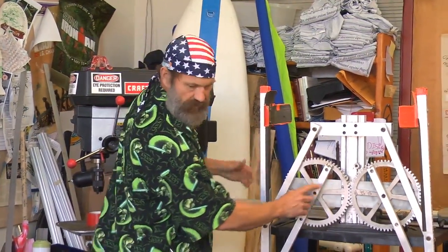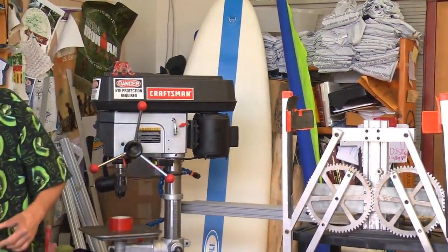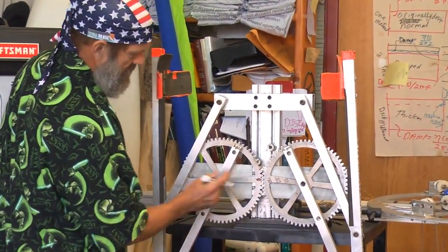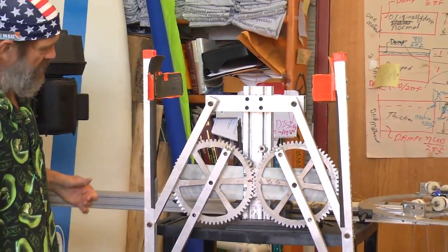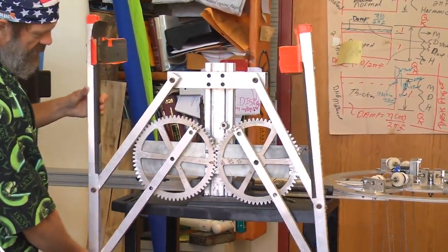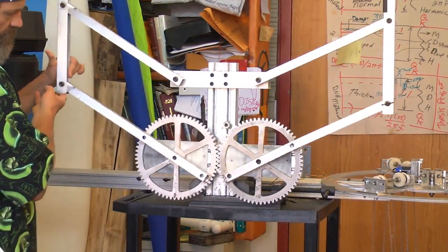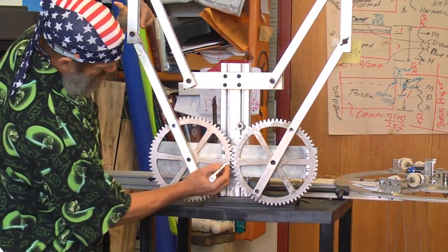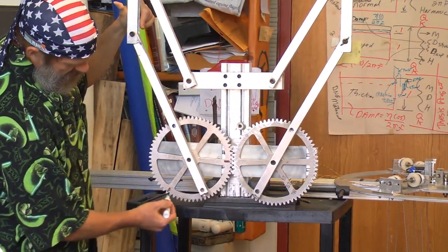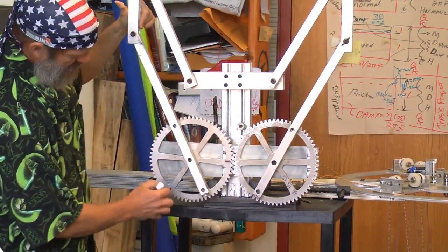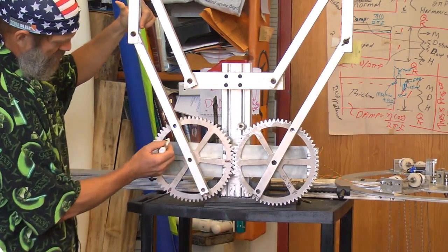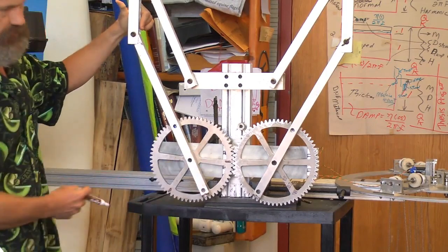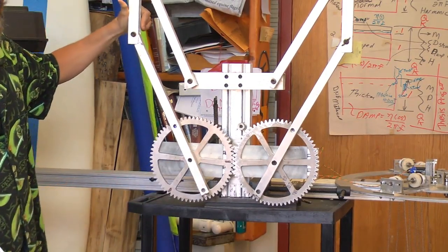Now also note on these gears here, if I put a little timing mark, that this is the position of the gear to start, and at the end, when the gripper is closed, it's around here. So this is an arc of about 120 degrees, and actually it's 1, 2, 3, 4, 5, 6, and I cover 2 of those, so it's exactly 120 degrees.